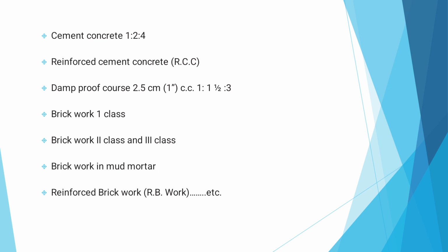Then finally, determination of bulking of damp sand by field test. Take a glass measuring cylinder and fill 3/4 of the cylinder with the sand under test and lightly tap the cylinder and read the volume of sand. Then pour water in the cylinder to submerge the sand and shake the sand well and allow to settle and then read the volume of sand.